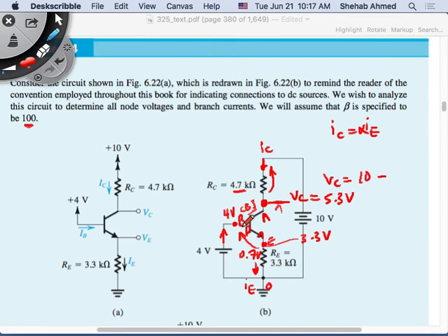It can even be 0, it's okay, and it can even be negative. VC with respect to VB can be negative 0.1, 0.2, 0.3. But if it's 0.4, then I'm starting to push this into forward bias. But now it's highly positive, so I'm reverse biasing this for sure, and this is an active region, right?